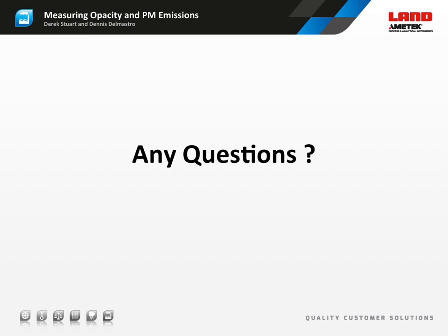Here's another question. What preventative maintenance is needed on an opacity monitor? There's very little preventative maintenance that's actually needed for an opacity monitor. You need to keep the optical surfaces clean, and you need to change the filter on the purge blower. That's pretty much it. And thanks once again, Derek.